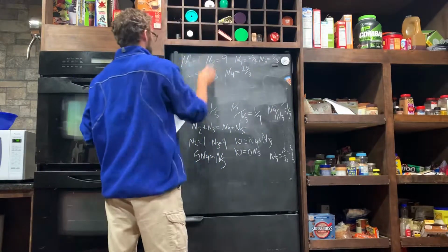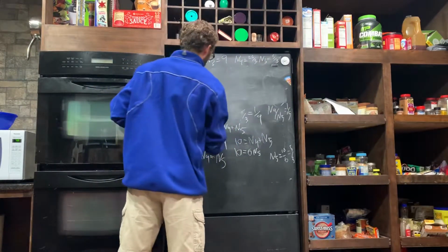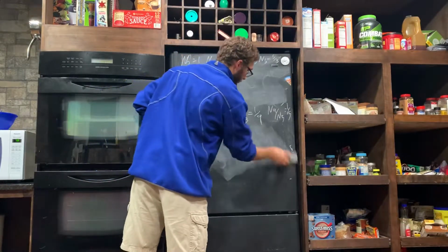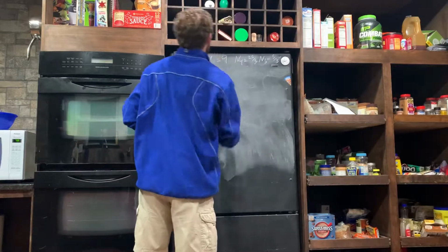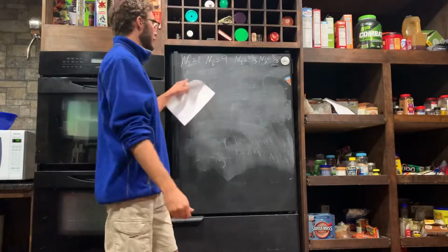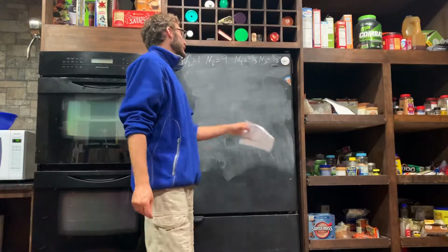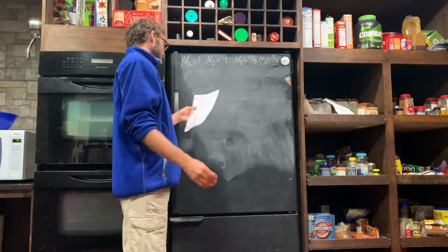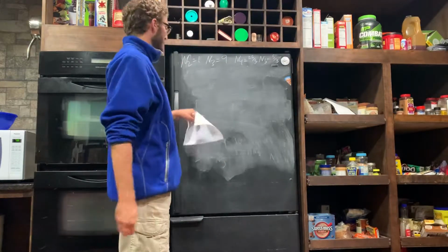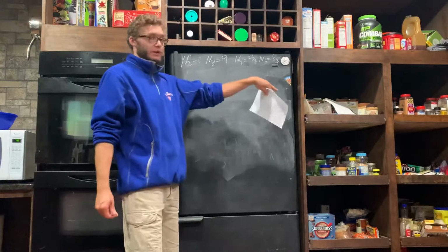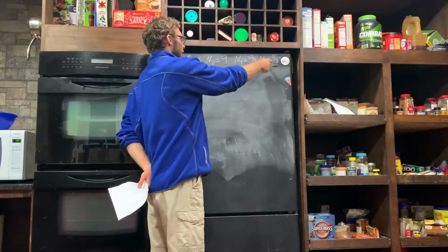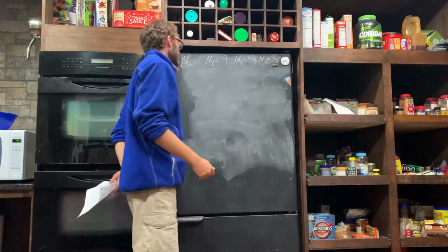Now we have the gear sizes. If we didn't have to worry about interference, we could just plug this in and it'd be good. But since we don't want any interference, we have to go back to the tables and look at our ratios. Let's say we multiply this out by 12, because of the 3 here, the least common denominator.